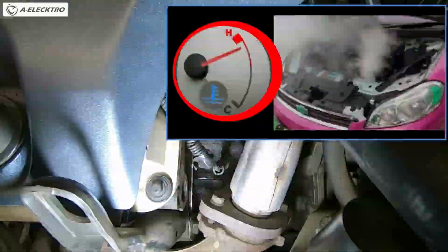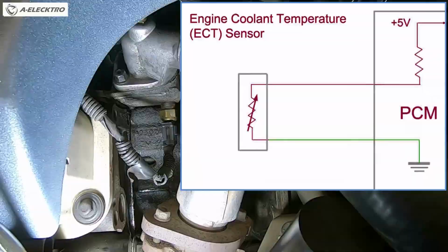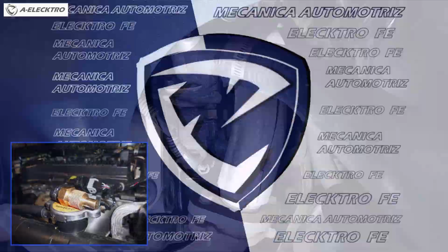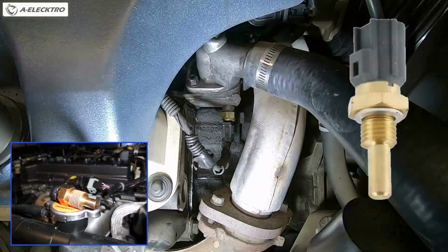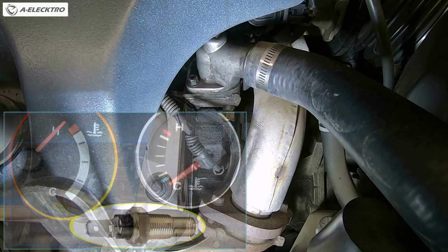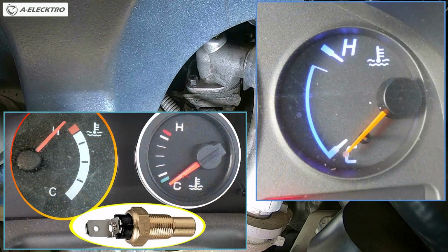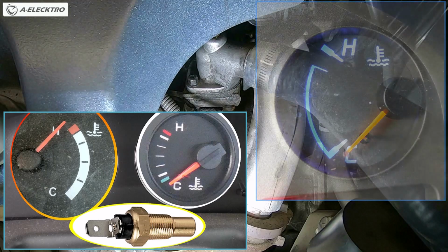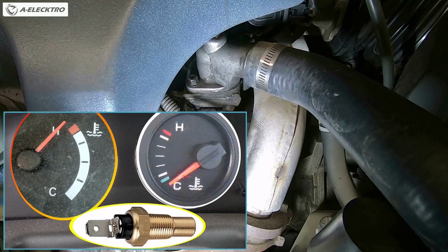In this case, the engine fans may not activate, which could lead to overheating. However, this depends on the vehicle system, since in some models, the same sensor that the computer uses also activates the fans. In others, there is a separate sensor for each function. If the fans are not activated, the engine can reach dangerous temperatures, which could cause severe damage if not corrected in time. It is essential to be aware of signs of overheating to avoid further damage.